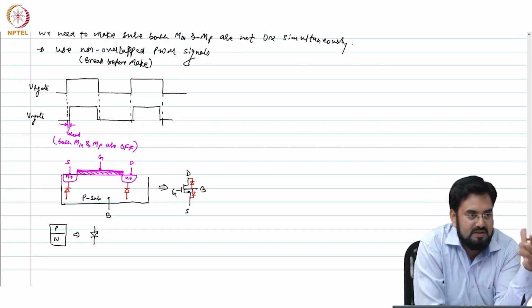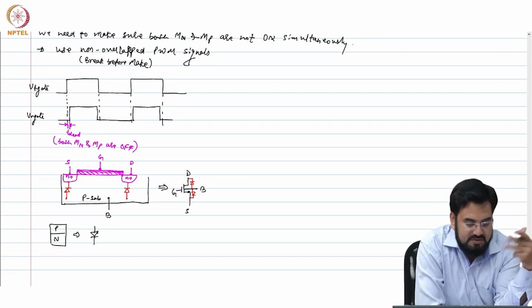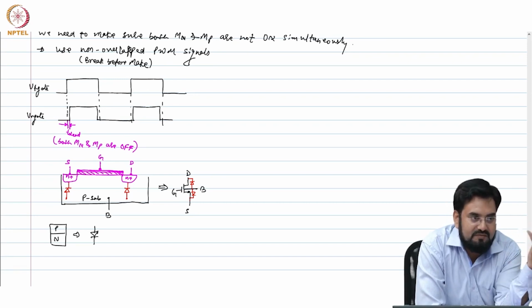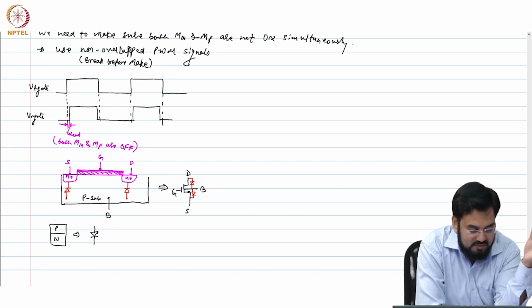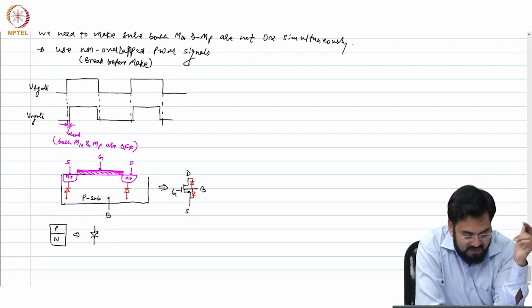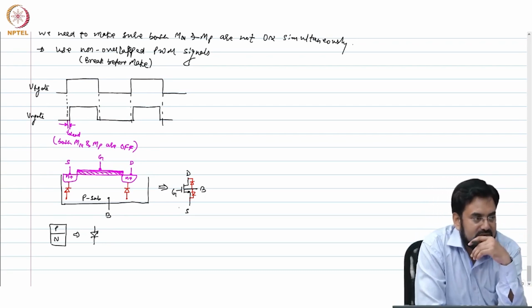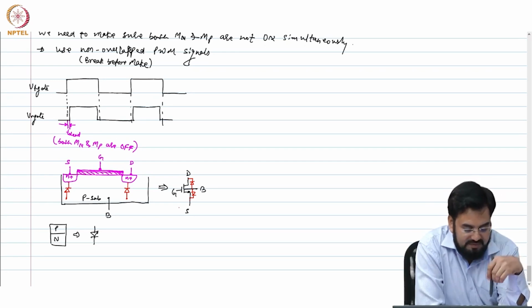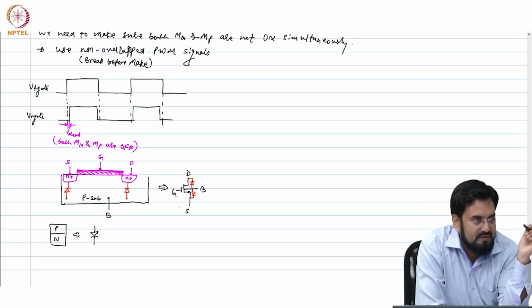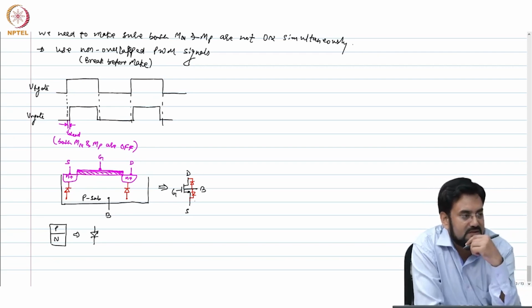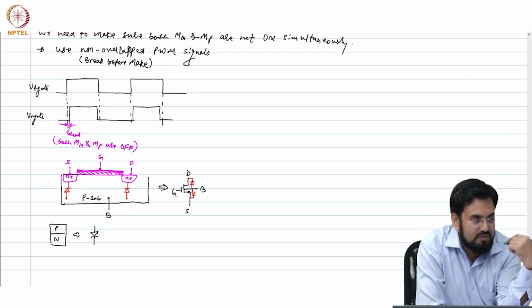In most of the cases the body is tied, for NMOS, to the lowest voltage because it is P type, and you don't want to forward bias the diodes. For PMOS it's tied to the highest voltage because the body is N type there, and source and drain diffusions are P type. So if you connect to the ground, the bottom diode will go away. The diode between bulk and source will go away if you short bulk to the ground and source is also grounded.